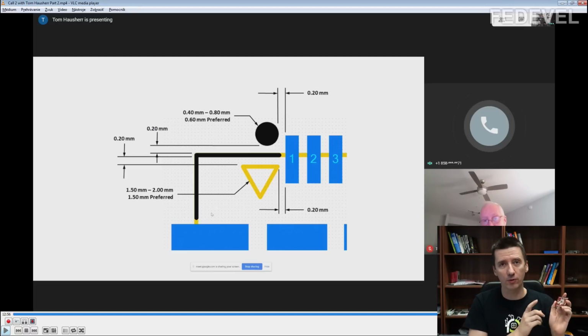So always when you receive a board, especially the very first prototype, the first thing I really recommend, and what I always do, is visual inspection. I have a look if the component pin 1 is correctly placed on the pin 1 location of the footprint. And that is one of the reasons why you really would like to have a visible pin 1 location on the footprint.